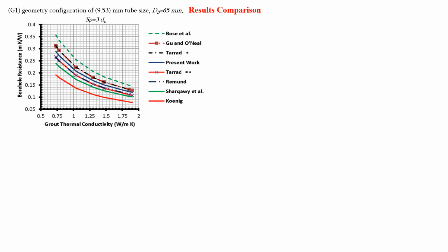All these correlations show that the trend of these values showed a decrease in the borehole resistance, the specific borehole resistance, as the thermal conductivity of the filling was increased.